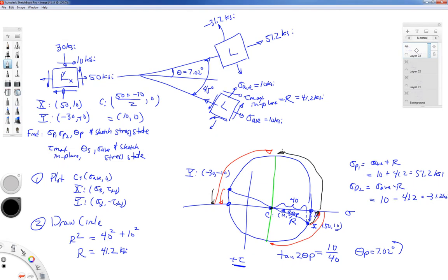the sigma axis, gone 90 degrees on the circle. I would have gone 45 degrees in the material from the principal stress direction. So that would make a 90-degree angle with the shearing stress block that I just drew. This would be 45 degrees from here to here. The reference is from the principal stress axis.